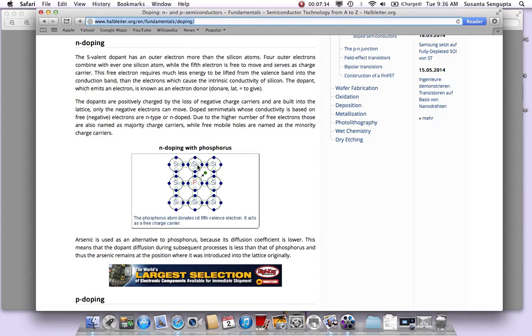Here is another silicon atom, here is another silicon atom. But what you could do is knock out a silicon atom and replace it with a phosphorus atom. It could be phosphorus or arsenic, one of them. So when you do that, let's take this example where it's phosphorus. Silicon has 4, but phosphorus actually has 5. So the phosphorus will come in and sit in between all the silicon atoms happily with its 4, but what happens to this 5th one?